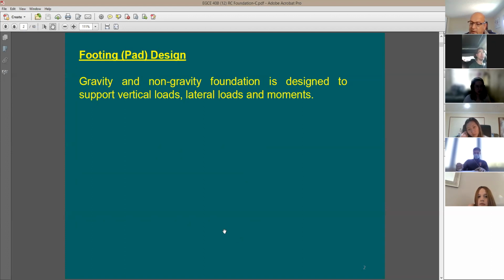It reminds me here with the column design that we have done. So in the column, first we say columns are going to be exposed to vertical loads, and then later on, we start to add moment on the column. So after that, we decide that columns usually support axial force and some moment on the top of it. Same thing with foundation, or with these footings or pads. Mainly, they are supporting vertical load. But in many cases, these pads or footings also support a little bit of a moment coming from the fixity of the column to the footing itself.